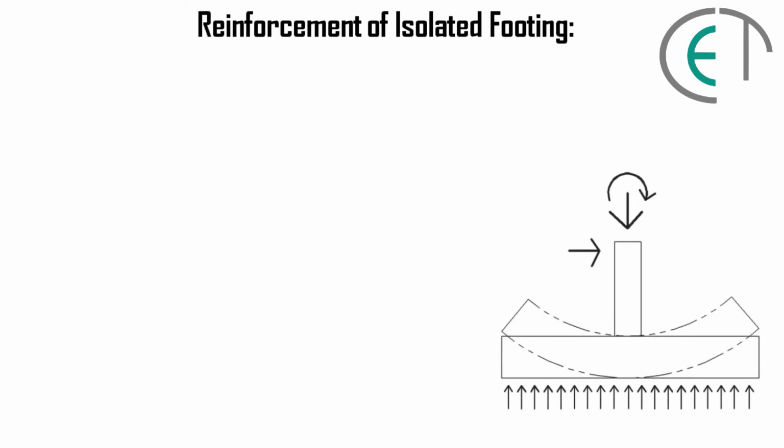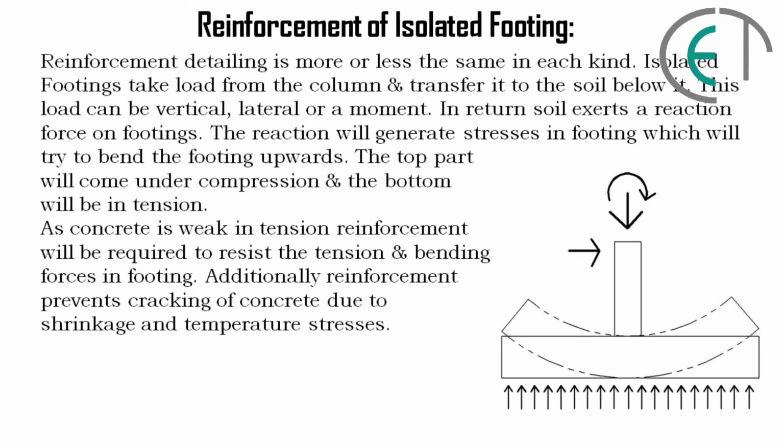Now let's discuss the reinforcement of isolated footing. Reinforcement detailing is more or less the same in each kind. Isolated footings take load from the column and transfer it to the soil below it. This load can be vertical, lateral, or a moment. In return, soil exerts a reaction force on footings.